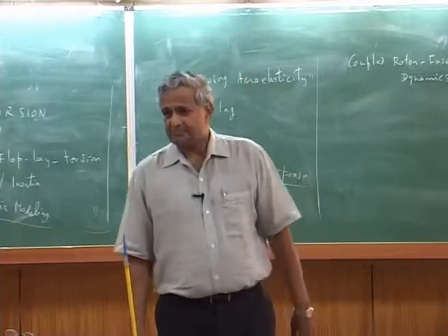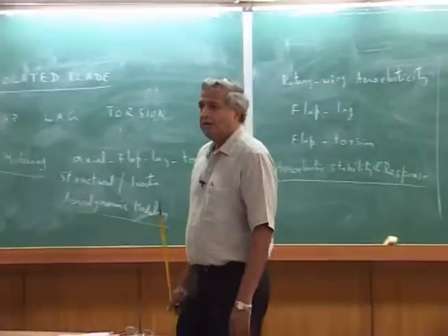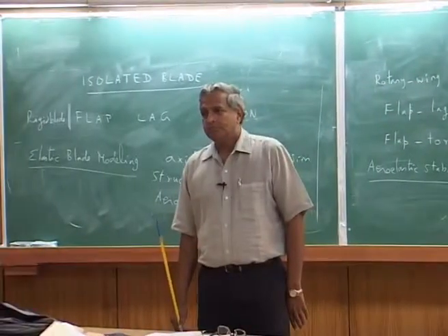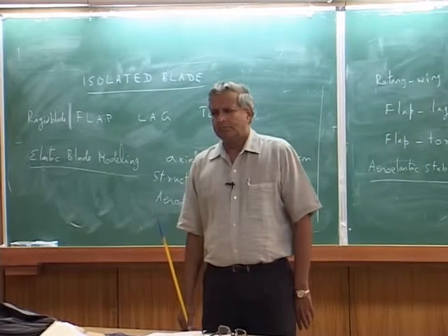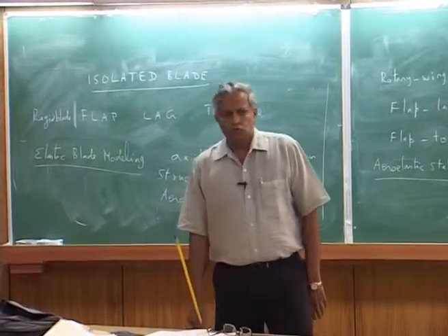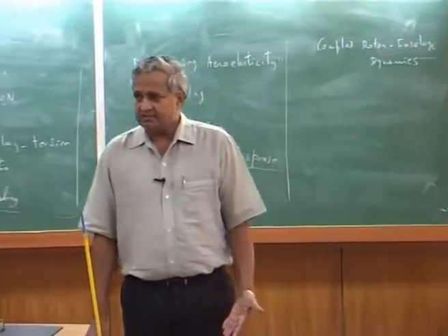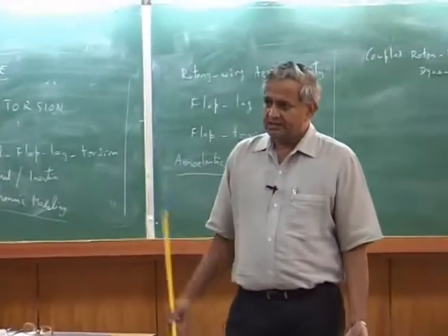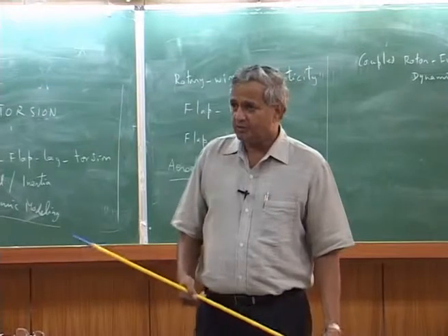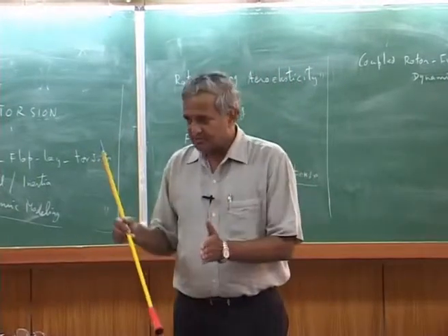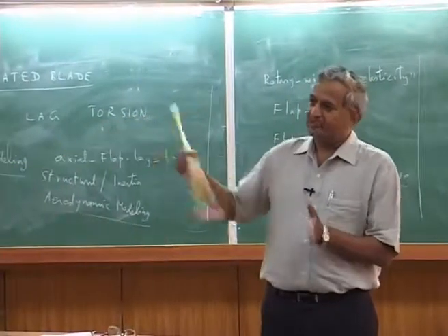That's all. So, one more note, sir. The blade hinge moment versus the EA, the blade stiffness. Blade stiffness would be far higher than the hinge moment which we are taking. What do you mean, the blade stiffness? Blade stiffness is EI. Yes, EI, sorry. EI in flap. Yeah, but EI is a variable. It's not uniform. See, from the aerodynamic section to almost near the tip, it's a constant value.